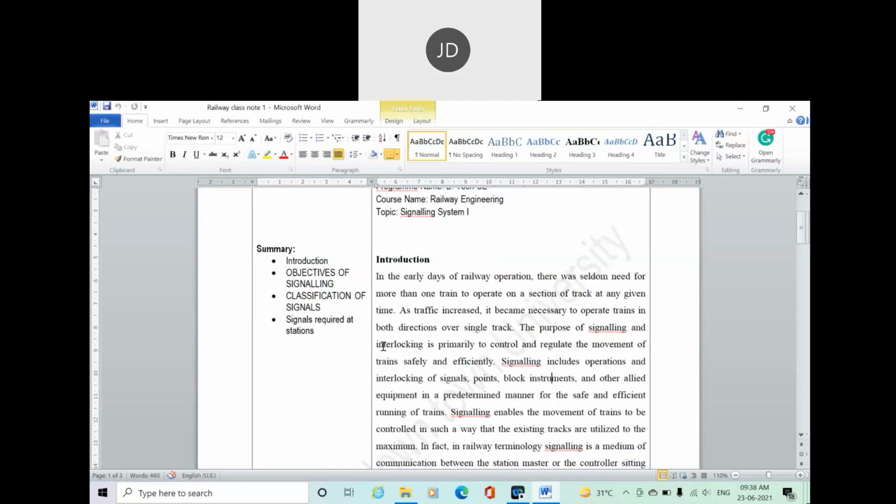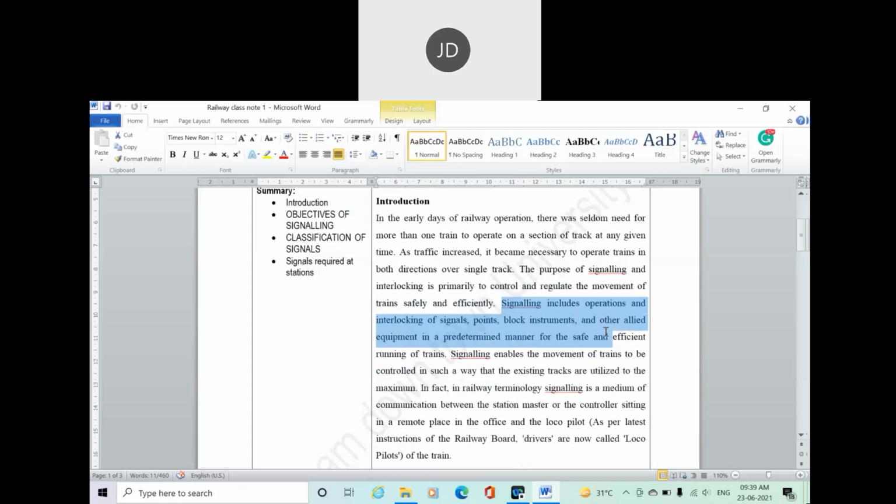Facing point locks are one of the most important safety features on the S&C layout. They ensure that the points cannot be moved when set. This is important because failure to lock the switches could cause a derailment. As engineers, we face an ongoing challenge to maintain and improve our switch and crossing assets. Trains can create large impact and lateral forces as they change course, and these forces can cause wear and deformation. Switches and crossings therefore have a limited lifespan before we need to replace them.